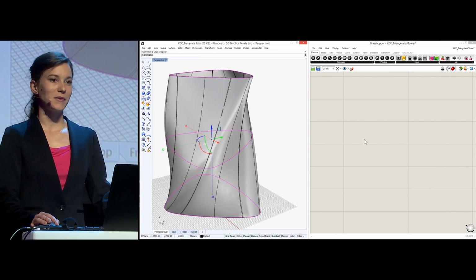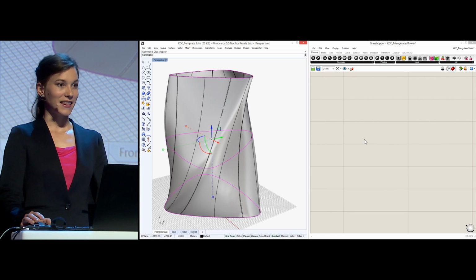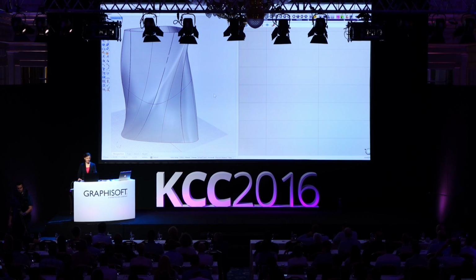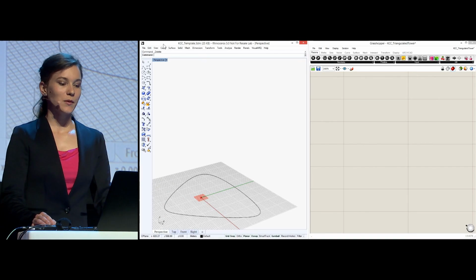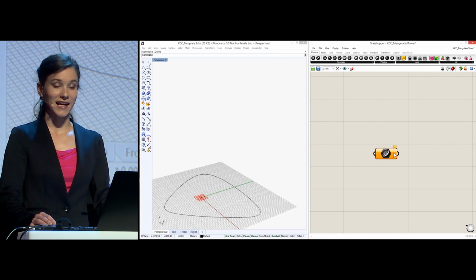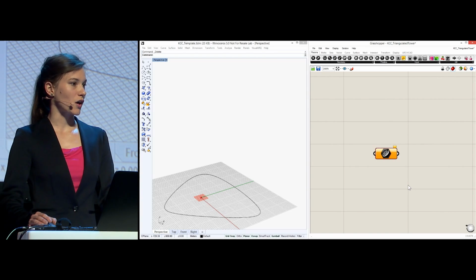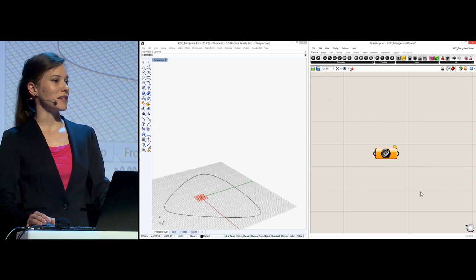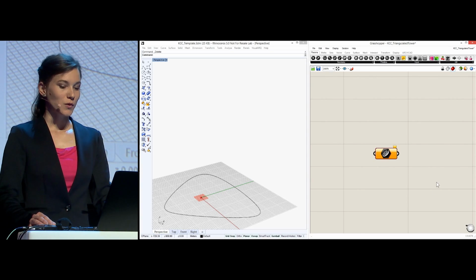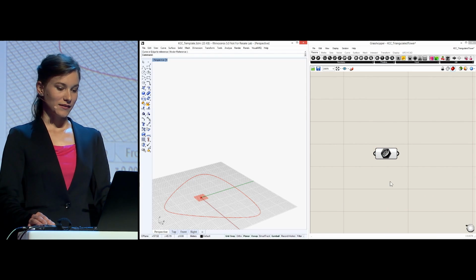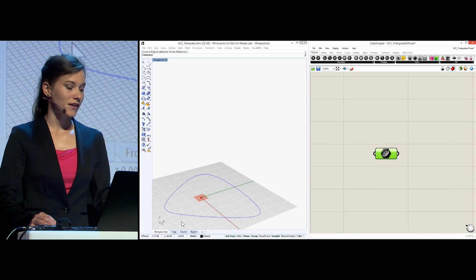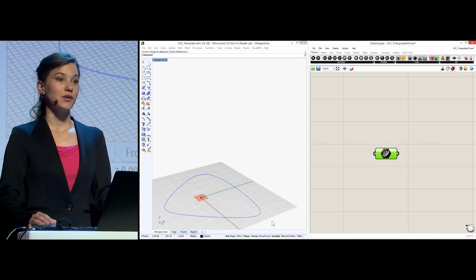Now, for those who are not familiar with this design environment yet, let me give a short intro. As an example, I will recreate the tower shape from scratch in Grasshopper. Now, in Grasshopper, there are nodes, small boxes like this. These are the building blocks of the algorithmic definition. They can be containers or operations. With this one, for example, I can create reference to the already existing Rhino curve here. So if I select this node, you will see this curve gets highlighted, indicating that the description of this geometry is now stored by this box.